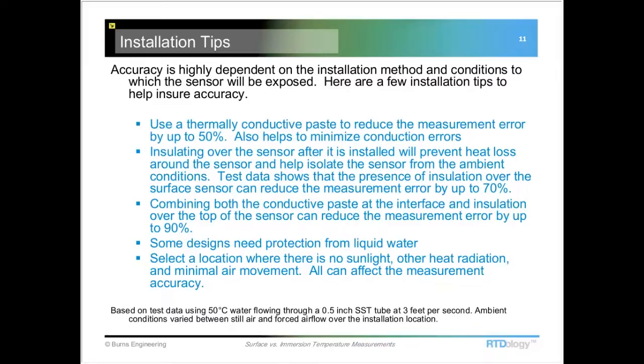And anytime we have a surface mount sensor, they're very susceptible to the effects of the ambient conditions. And having more intimate contact between the sensor and that surface helps minimize those conduction errors.